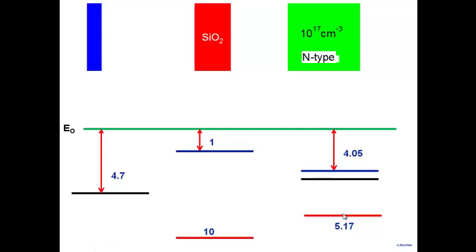Now you put them into contact and see what happens here. If you put them into contact, you will say that equilibrium will occur. You would want electrons to go from higher energy to lower. And if it's bothering you, how will it go through SiO2? Remember that I can also short these two together by a wire and bring them into thermal equilibrium. So don't let that bother you. Think that the electrons are transferring, because I've connected them up through a wire here.